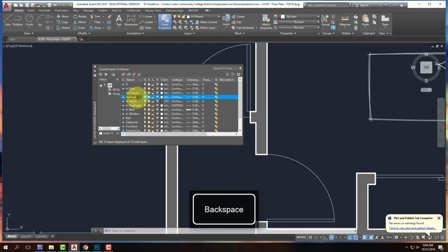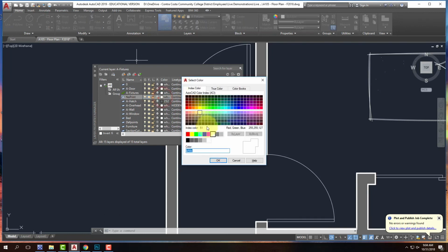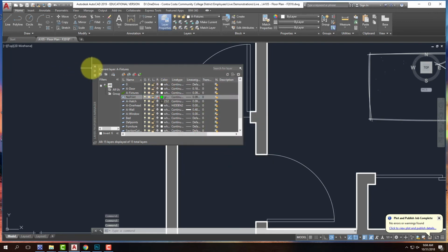And when you are done creating that layer, the little printer icon, you want to click on it. It gets a red circle. That means it's not going to print. And also, personally, I always color my non-printing layers green. It's just habit. It doesn't mean that you have to do it, but that's just something I do. And so I'll have my no print layer set as green.